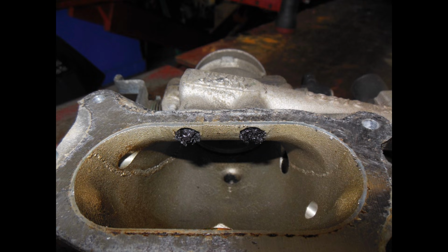In any regard, if I can make some time here, I'll go out and put that vacuum back on the EGR valve like I did before. And now with this thing cleaned out, that engine should very closely come to a stall, or actually stall, just to show you how a properly functioning system should test.